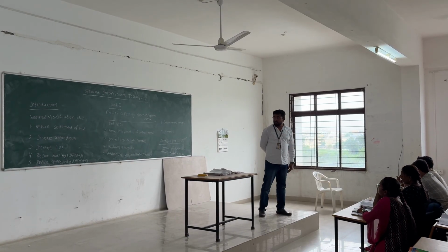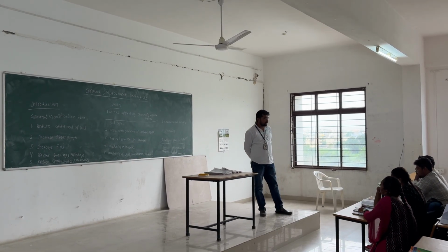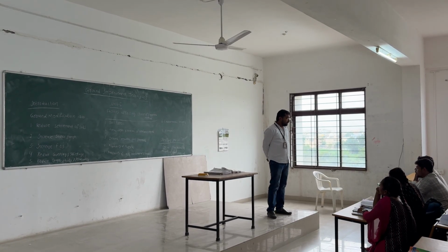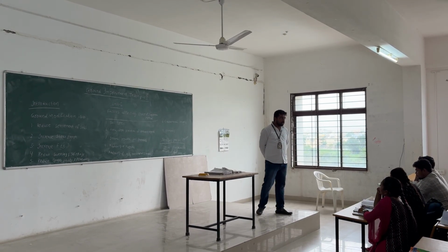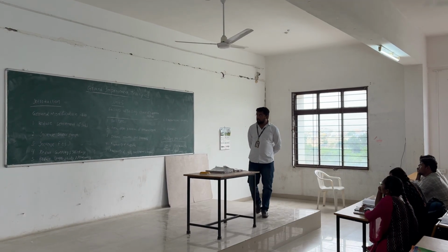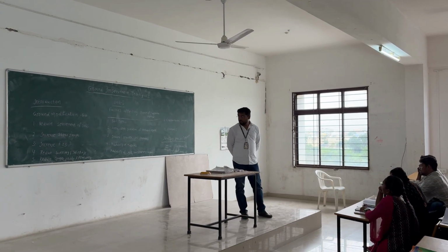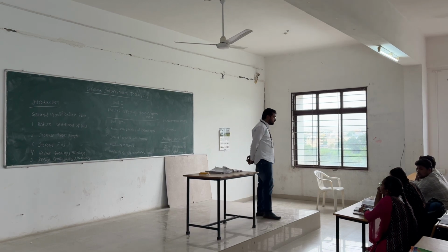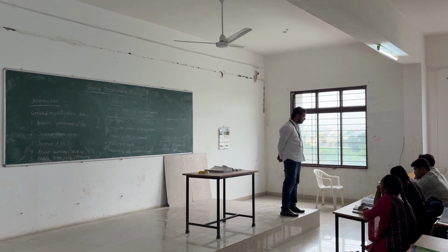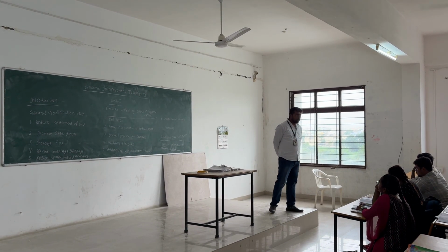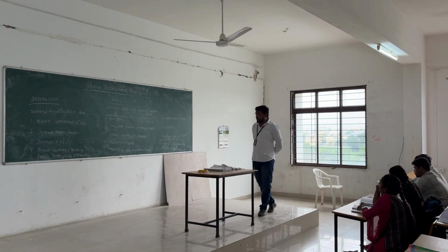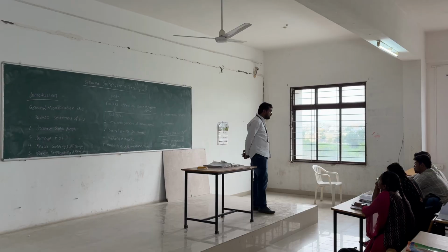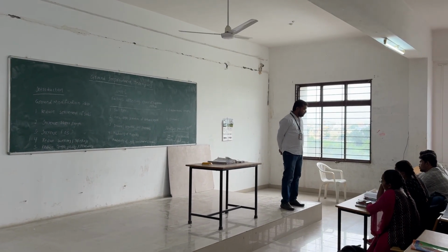To increase the shear strength, suppose the soil is soft, at that time we are going to increase the angle of internal friction. That is, we are going to increase the phi value by mixing red soil with the clay soil. Similarly, how do we increase the factor of safety? Whenever the soil is strong, whenever the soil is good, the factor of safety will increase. Whenever the factor of safety is good, only then will the soil be in a stable condition without allowing failures.